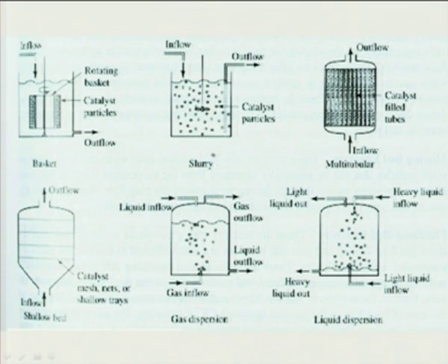Then the second is the slurry type of reactor. Here, reactions with slurry containing solid particles that can be physically separated from the suspension fluid are carried out. The tank is an agitated tank. These reactors are simple in design and they have good transport properties, especially for highly exothermic reactions. Sufficient control can be provided over the reactor conversion and performance without any compromise to catalyst access. In fact, catalyst particles can be added or removed continuously through the flow of slurry. However, the one major demerit is erosion in this reactor.